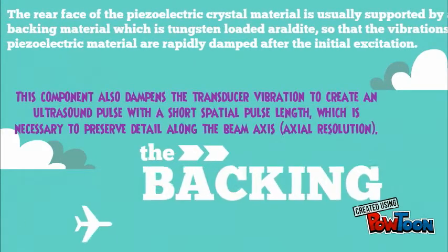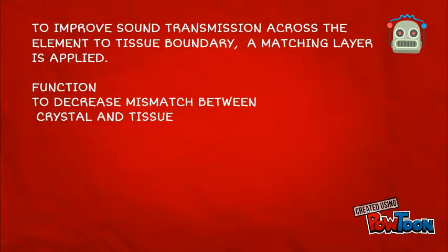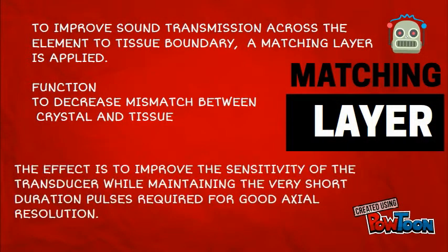The rear face of the piezoelectric crystal is usually supported by backing material. This component dampens the transducer vibration to create an ultrasound pulse with a short spatial pulse length, which is necessary to preserve detail along the beam axis. To improve sound transmission across the element to tissue boundary, a matching layer is applied. Its function is to decrease the mismatch between crystal and tissue. The effect is to improve the sensitivity of the transducer while maintaining the very short duration pulse required for good axial resolution.